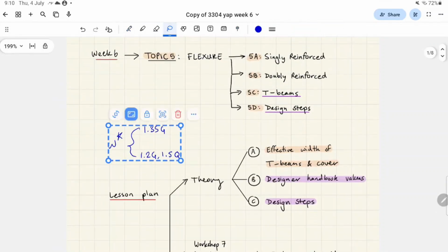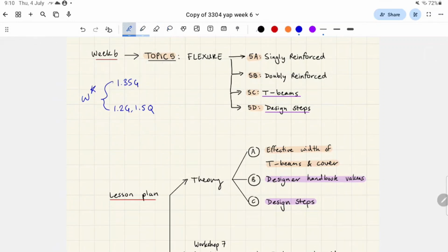Specifically, if you've done steels, let me just run through how steels worked. Say you're doing tension design in steel. You calculate the external axial load being taken by the steel member, and it has to be less than your ultimate tensile axial force in strength design.